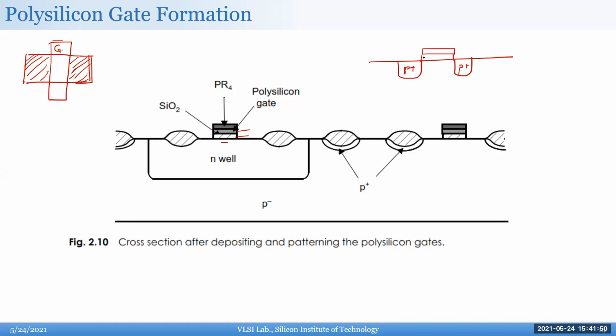The problem with this, like I said, is that it needs to be perfectly aligned, but it's very difficult to align. Right now you have 2 to 4 nanometers of this thing, and in most processes, when you align it, you can't even get within a nanometer. So what will happen is you do your P plus first, and then when you do the gate, it'll be shifted like this. So this is open, because you don't have a gate in this area. This will become an open device.